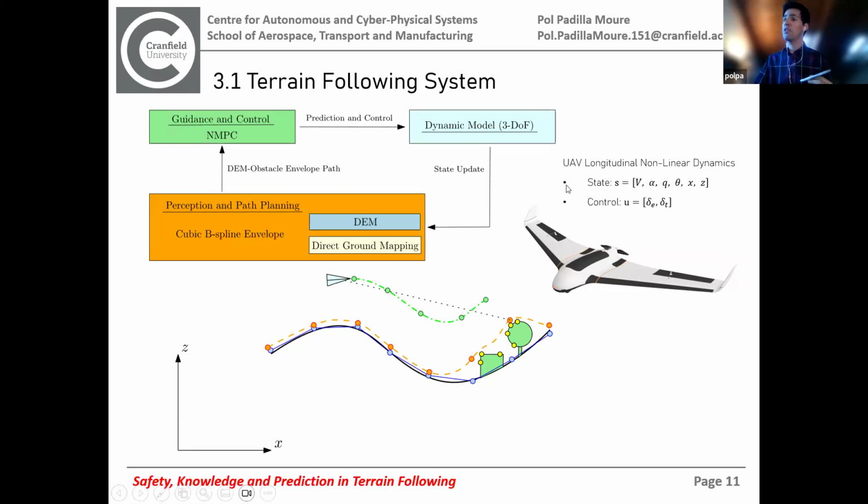So if you were just trimming the aircraft, you might not need to include the position in your states for the NMPC, but because you need to know the aircraft relative to your envelope, you must now include the position as a state directly for your NMPC.